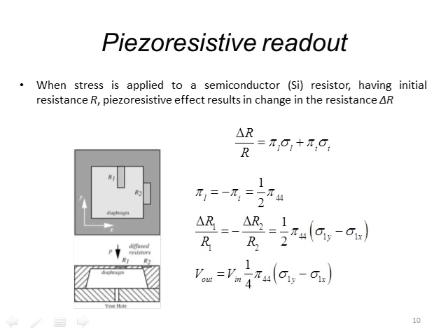So you know that silicon is a semiconductor, and when we add dopants, we can increase the conductivity. So in these regions, R1 and R2, we add impurities. Let's say that we add boron, okay? And in those regions, then, we can make a pretty good resistor. And this resistor then becomes a piezoresistor because it's made of silicon, and we know that silicon can be a piezoresistive material.